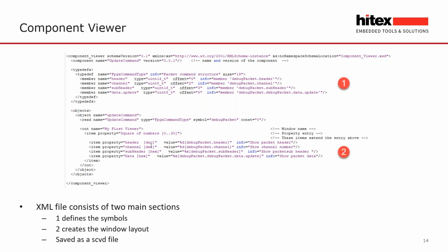These views we can make for ourselves, and it's relatively straightforward and a quick job to set up a basic view. As you're writing and developing your application, over the lifetime of the project, you can start to build these component views, which take probably a couple of hours each. Then within the debugger, you can get a detailed view of the key variables that are in your software.